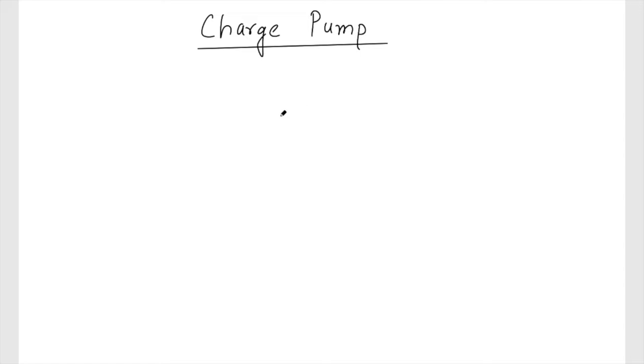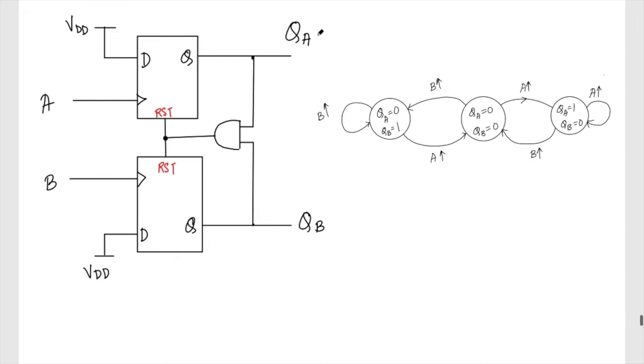which is used to convert the phase difference that we have got, QA and QB, the information that we have got. We have seen that if the phase of A leads the phase of B, then the average value of QA is always higher, and B will always be 0. Similarly, if the frequency of A is higher than B, then still QA will have a lot of pulses.